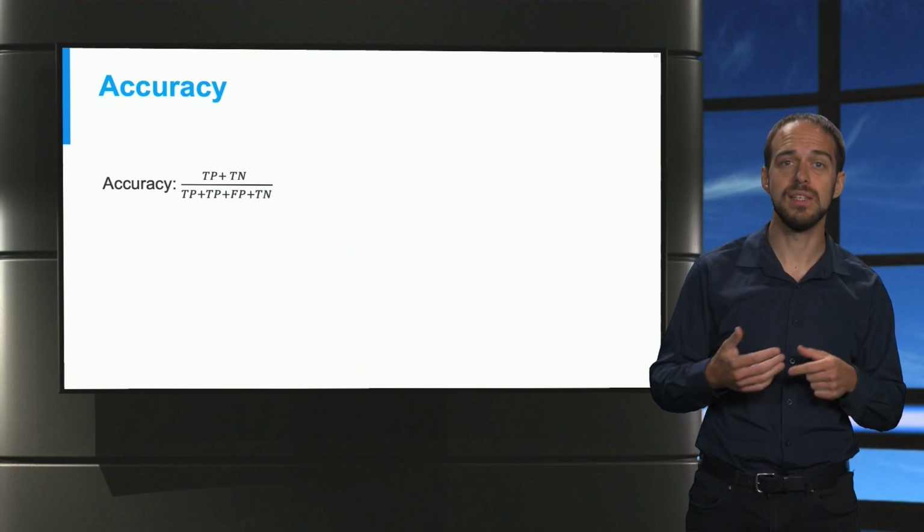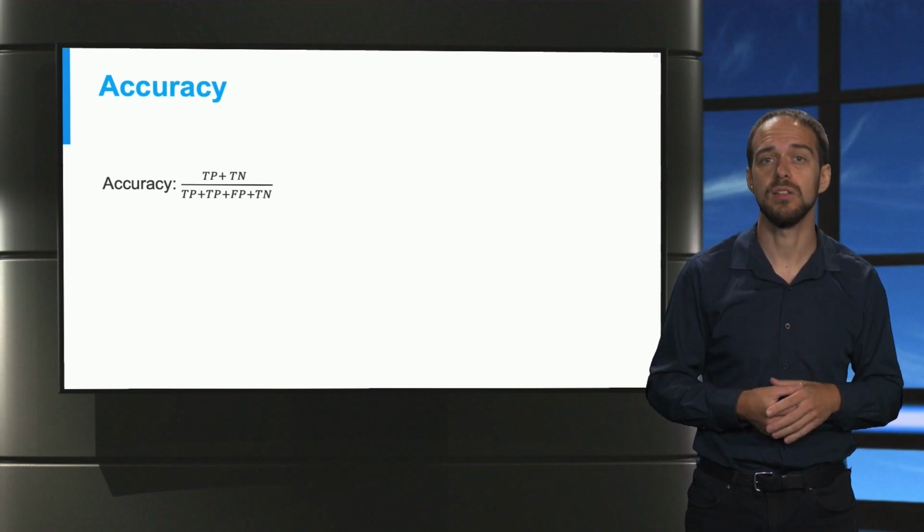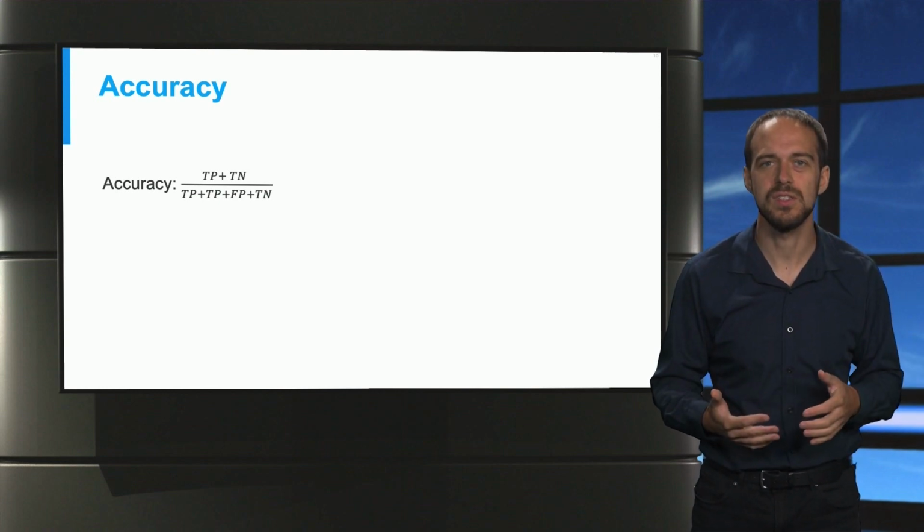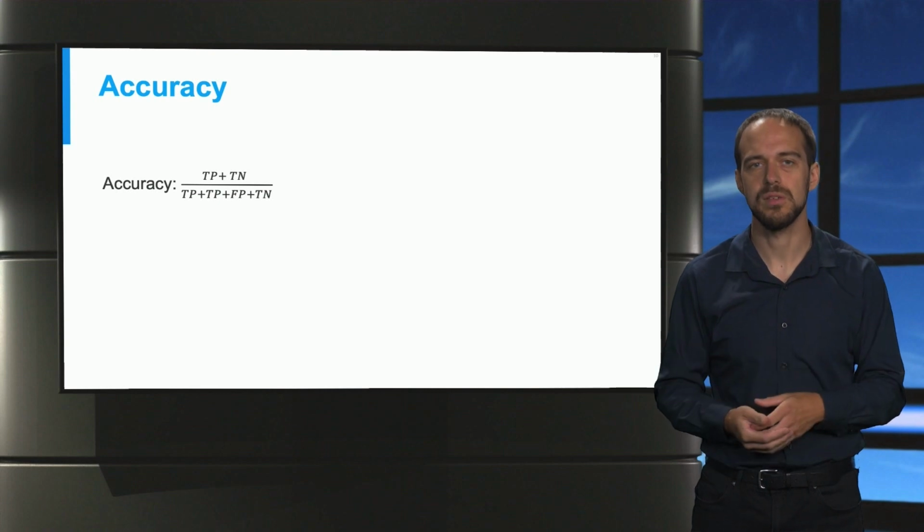Accuracy, specifically for DSA, is a significant subject. The accuracy is the correctly predicted operating conditions divided by the total number of conditions. However, sometimes it is worse to predict one class more inaccurately than the other. For instance, in DSA, to miss an alarm for insecurity is significantly worse than having a false alarm. For false alarms, we perform further analysis and place preventive control actions, but a missed alarm could lead to a total power blackout of the system.